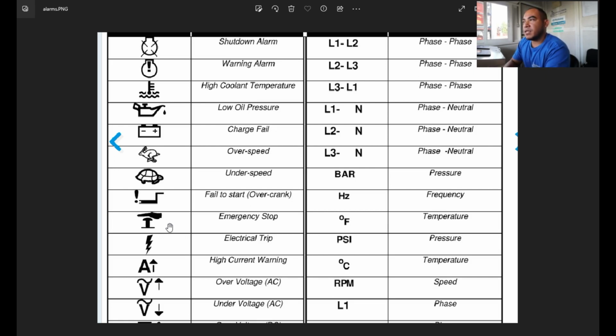Either somebody pushed the emergency stop button, or sometimes the wiring connection is loose, or there is a faulty contact inside of your NC, or normally open, or whatever contact you are using for this emergency stop. You have to check if the contact inside is working or defective.